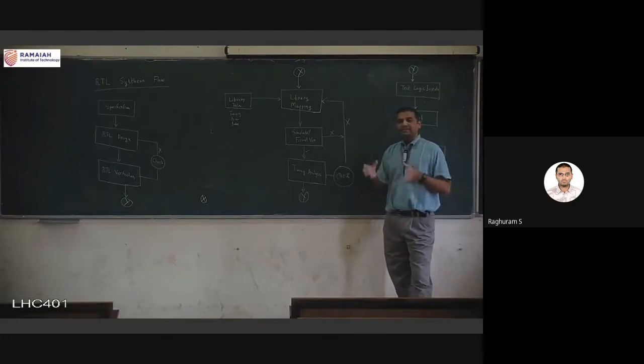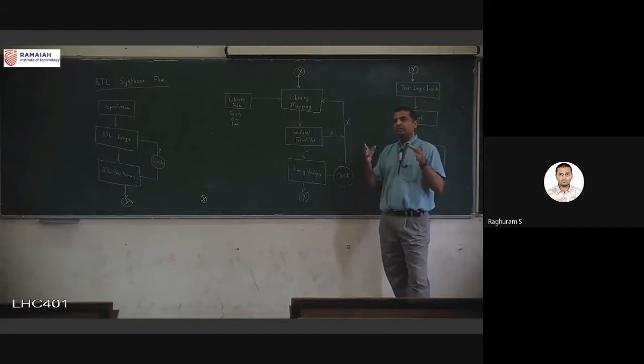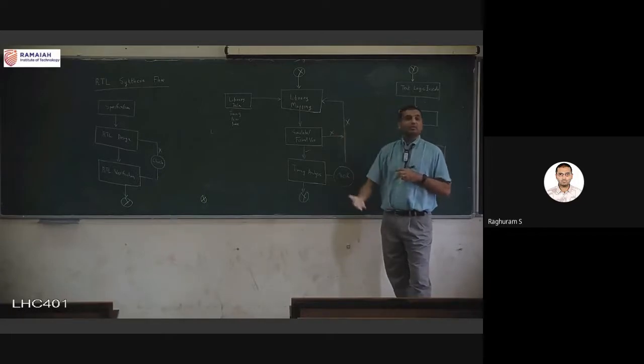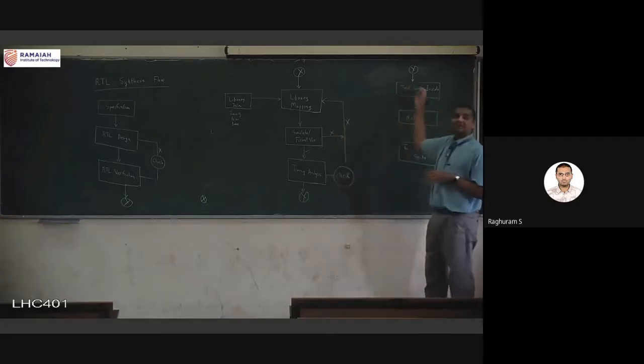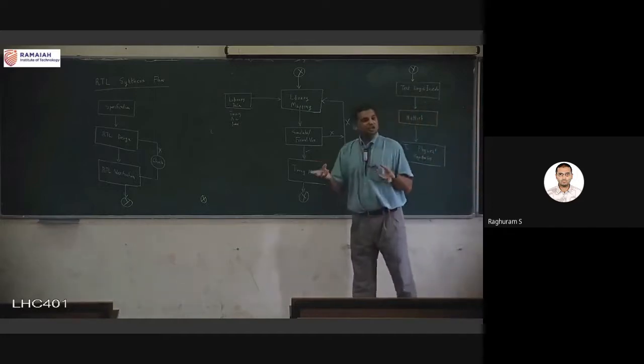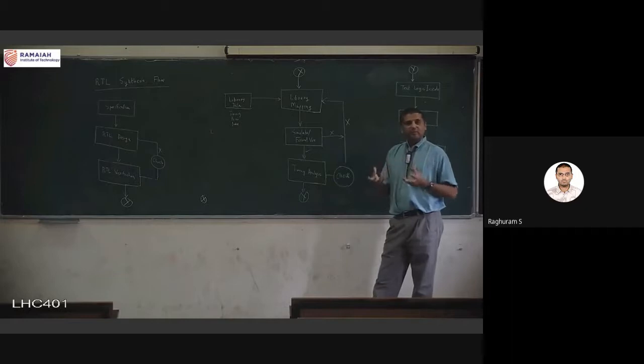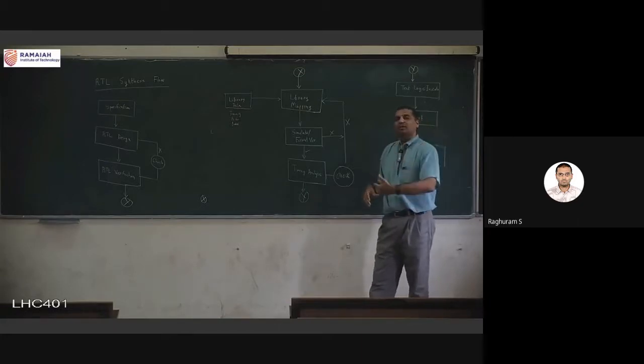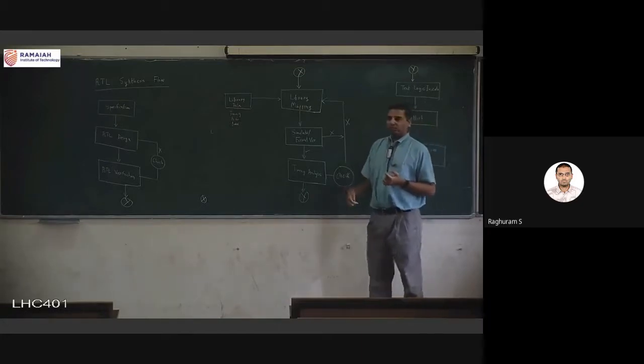And if it is in test mode, that means that the inputs of the gate are coming from a different source. Where is it coming from? That is this test logic. So these are all special registers, for example. They could be special logic also sometimes. But generally, these are a different set of inputs which are easily accessible. These are not the primary inputs. These are easily accessible, and through these, I will feed whatever pattern I want. I cannot do that otherwise.